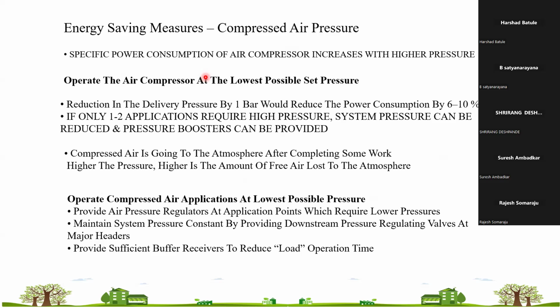But you cannot set your compressor at 13 bar and then reduce the pressure at your user end by FRL and similar methods, generating pressure at 13 bar and using it at 6 bar. You are consuming more energy to produce the same amount of compressed air, because you are like throttling the valve at the user end. An ideal pressure setting has to be there.